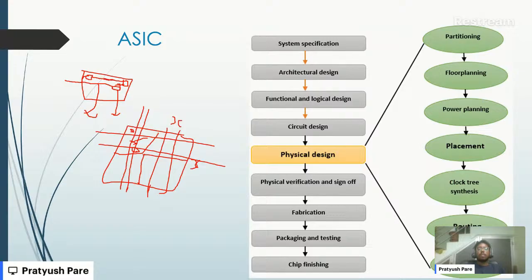So it will receive one data faster and the other data later. That will be an issue, right? So we should not do this. That's why we have many different architectures, this problem statement of clock tree synthesis, how to do it. In general, we add some more delay in order to compensate for this wire delay, and we get the data in time. That is how clock tree synthesis is done.